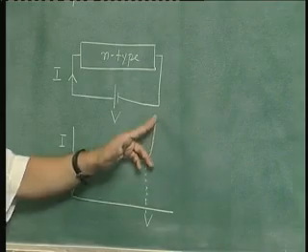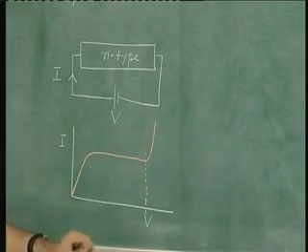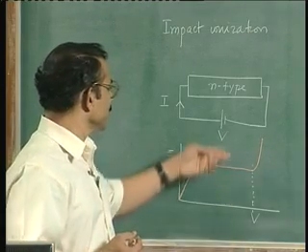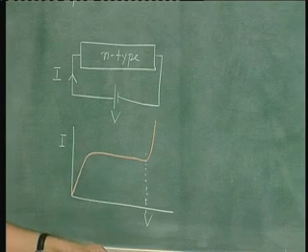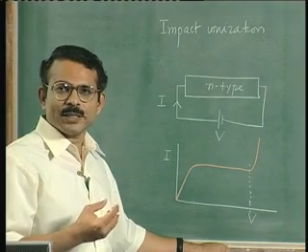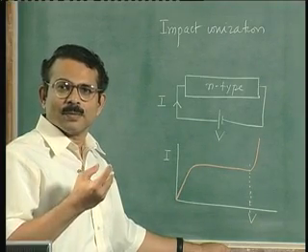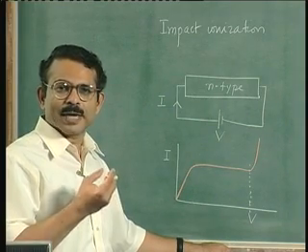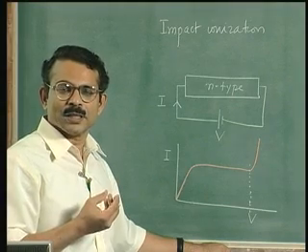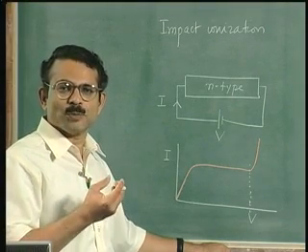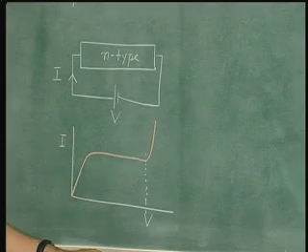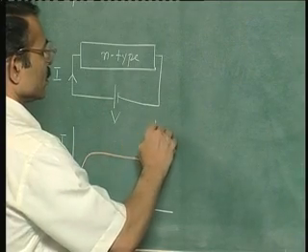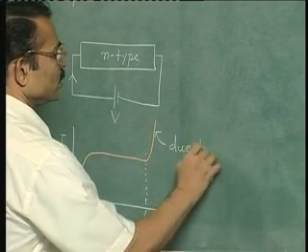So here the carriers are increasing in number beyond this limit, because between any 2 collisions the carriers are gaining energy from the electric field that we have applied, and this energy that is gained is so large that the carrier, when it collides with a silicon atom, can break a bond and generate excess electron hole pairs. So the energy gained by the carrier between 2 collisions is more than the energy gap. Now this is the situation of impact ionization. So this is due to impact ionization.